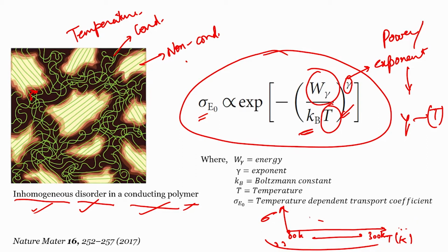What is the reason? At lower temperature the thermal vibrations, which cause inadvertent transport from one conducting island to another, would otherwise dominate the intrinsic or natural transport phenomena. That's why, in order to negate the temperature dependent transport, they go to low temperature, and then as a function of temperature they try to see how the transport phenomena evolves.